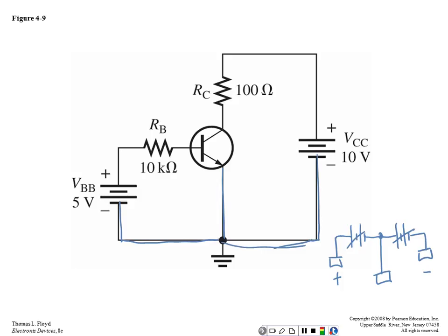And then what you're going to do is calculate. You're going to use RB to calculate your base current. You're going to use RC to calculate your collector current, right? You're not going to use a current meter. And you're going to find out that the actual true current meter is probably the least often used meter of the three that you have available.